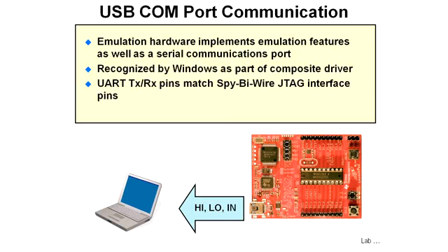Now, if you're dealing with a part like the 2553 that has a hardware UART on board, those UART pins are directly connected to the peripheral UART inside the device and work in a similar fashion. Now, like I said, the UART is connected to the emulator. The emulator sends that information via a virtual COM port back to the PC.